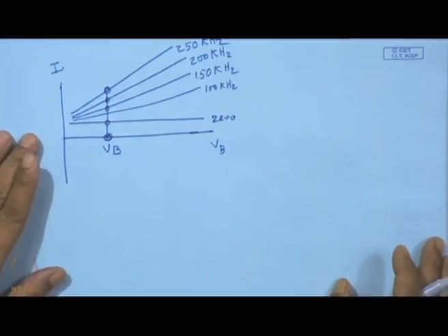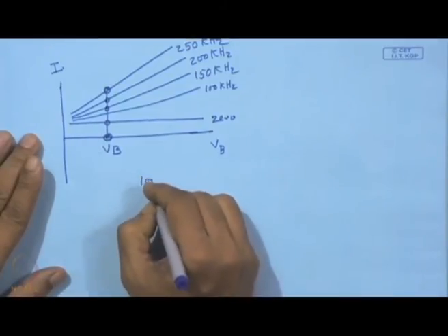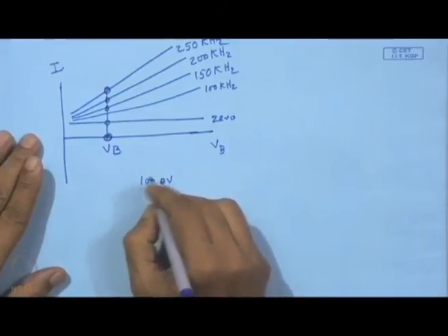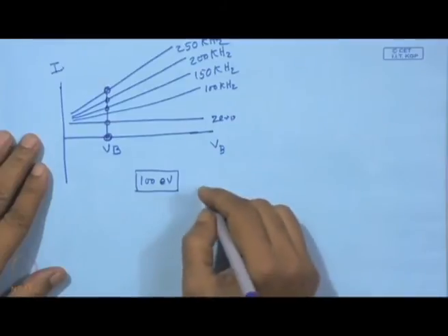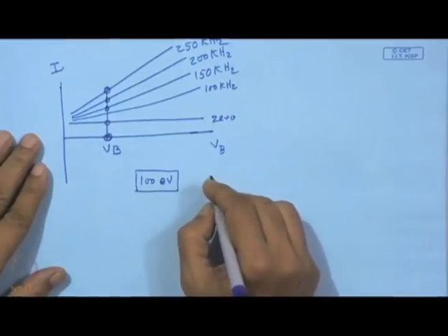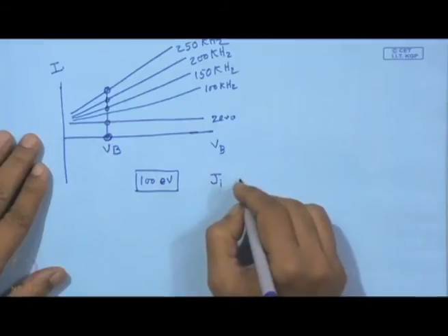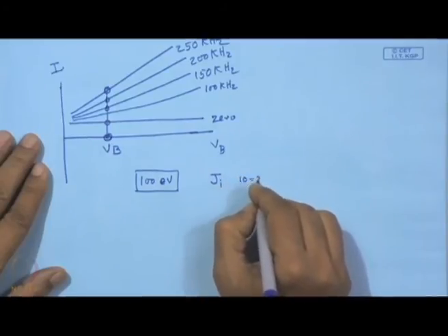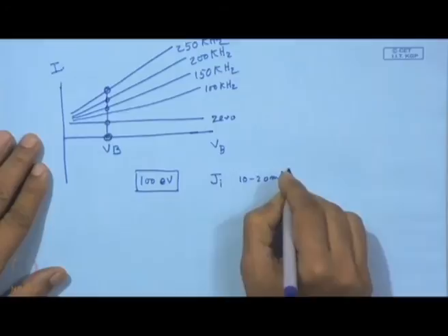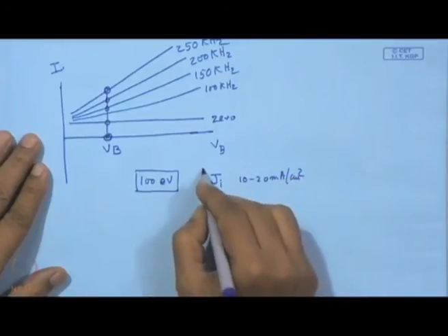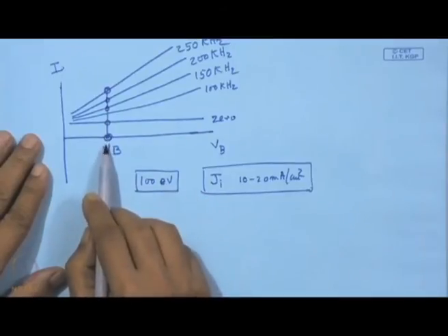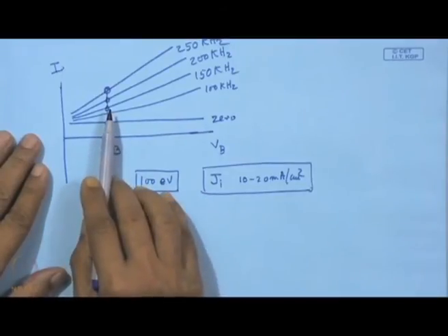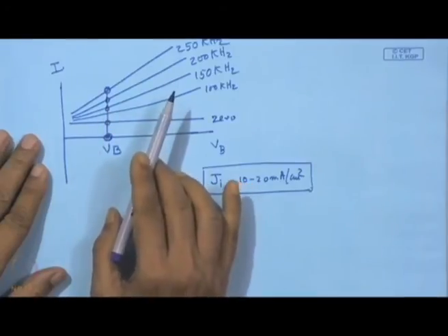That means, with low ion energy, less than minus 100 electron volt, we should be able to draw current such that the ion current density is in the order of 10 to 20 milliamp per square centimeter of the substrate. This is a very important parameter, and we can achieve it just by enhancement of the pulse frequency with this DC supply.